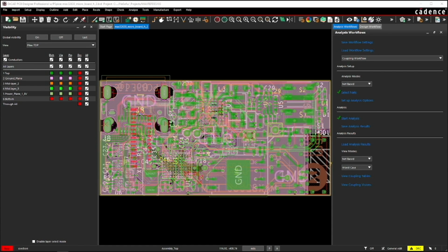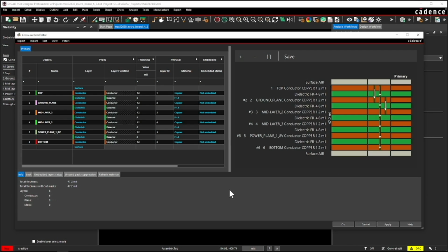When you're reusing sections of your own design or some other design, you have to check data sheets for matching voltage levels just to make sure that it matches the devices you're using. You also need to watch out for current demands. Then you want to make sure that you make your traces wide enough because they may need to be different from the trace widths in the original reference design. Also, whenever you need to have controlled impedance traces like this design does, you want to make sure that your stackup accommodates the proper impedance for the traces you're using.